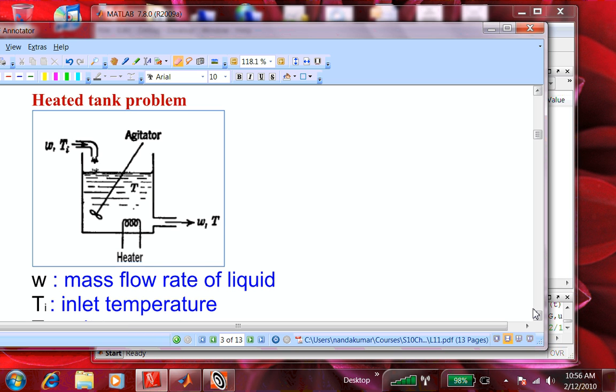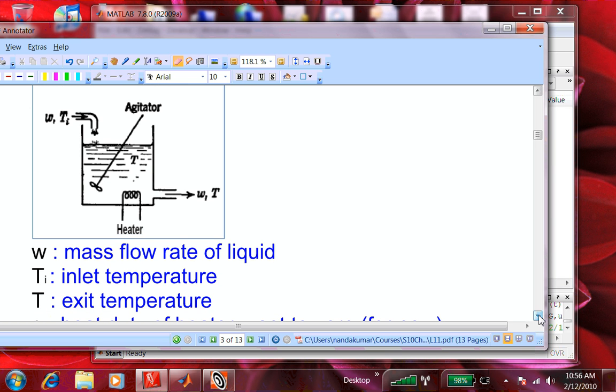So if I give you a problem, analyze the problem, do the Laplace transform, derive the transfer function for the physical problem. It could be a reactor, it could be a separation unit, a heat exchanger, whatever. So let's revisit this particular problem where we have a heated tank with a heater. This is the very first problem that we started the course with. The inlet and outlet flow rates are the same, so there could be variations on this. In this example, the level doesn't change because the inlet and outlet flow rates are exactly the same. The inlet temperature is something that I can change, with a step change or impulse change or whatever, and I'm monitoring and controlling the outlet temperature, which is the same as the temperature in the tank.